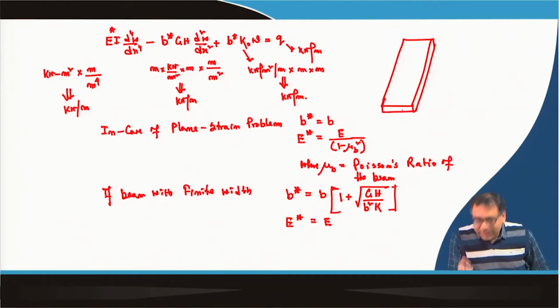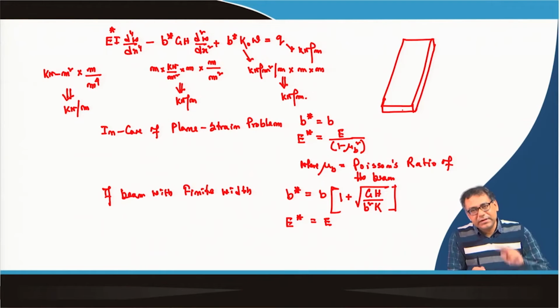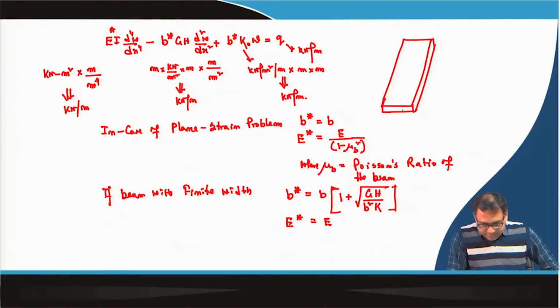Now, this strip footing kind of foundation you can analyze in two ways. One is beam under plane strain condition and beam with finite width. So, if beam with finite width, in that case length will be infinite, and if the beam is under plane strain condition, then your length will be finite. For example, first case I am considering that beam